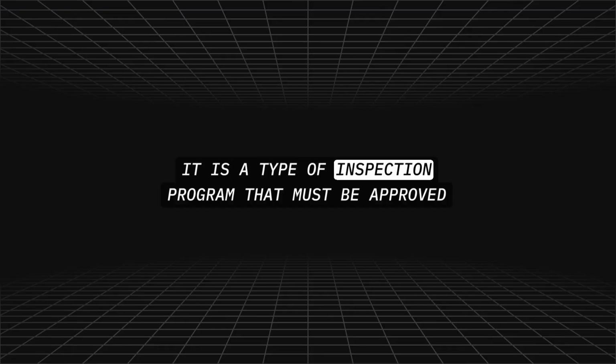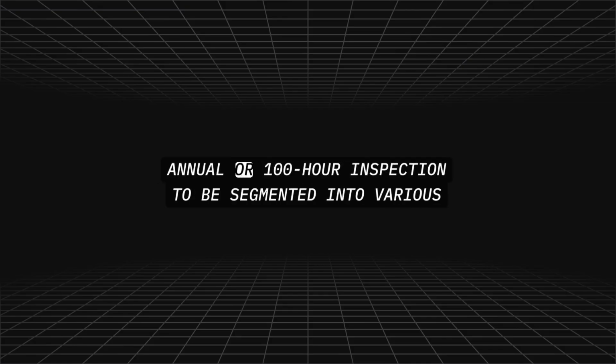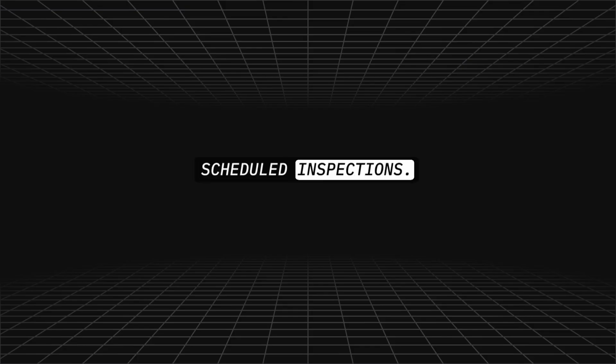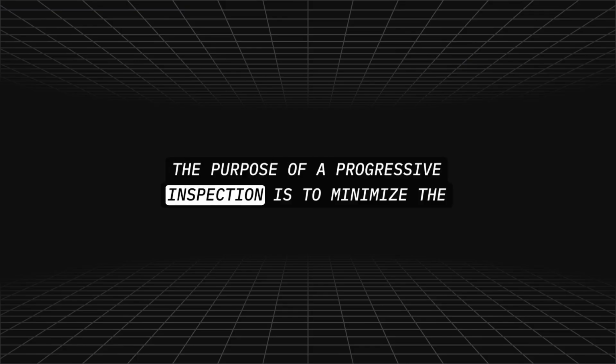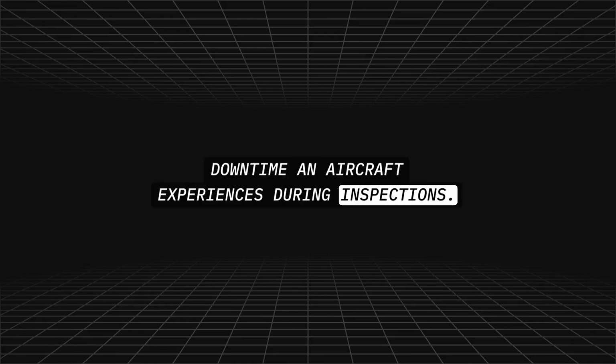It is a type of inspection program that must be approved by the local Flight Standards District Office that allows an annual or 100-hour inspection to be segmented into various scheduled inspections. The purpose of a progressive inspection is to minimize the downtime an aircraft experiences during inspections.